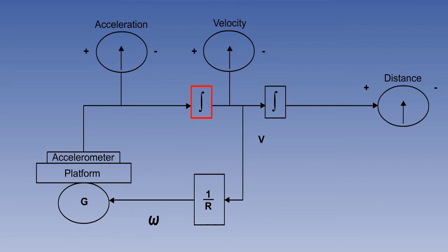The acceleration goes to a first stage integrator, where it becomes velocity. The velocity goes onwards to the second stage integrator. But again, we can monitor it with our next imaginary meter. And again, vertical means zero output, left means positive, and right means negative. Here's the second stage integrator, with its output of distance, for which we use the same convention. It's just easier in this diagram to see a needle presentation than changing digits for latitude and longitude.